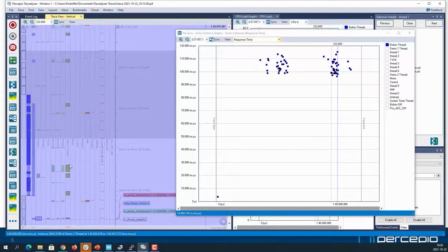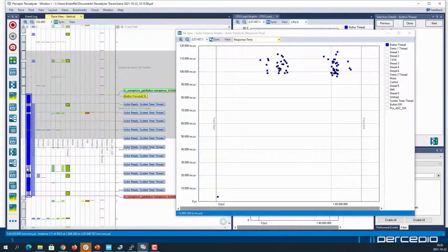And as you can see here, it's quite obvious why it took longer in this case, because there are several occurrences here when the task would like to execute, but there is some higher priority task that is executing instead. So here, for example, this one is executing, and in this time slot down here, you have several different tasks with higher priority that are executing.